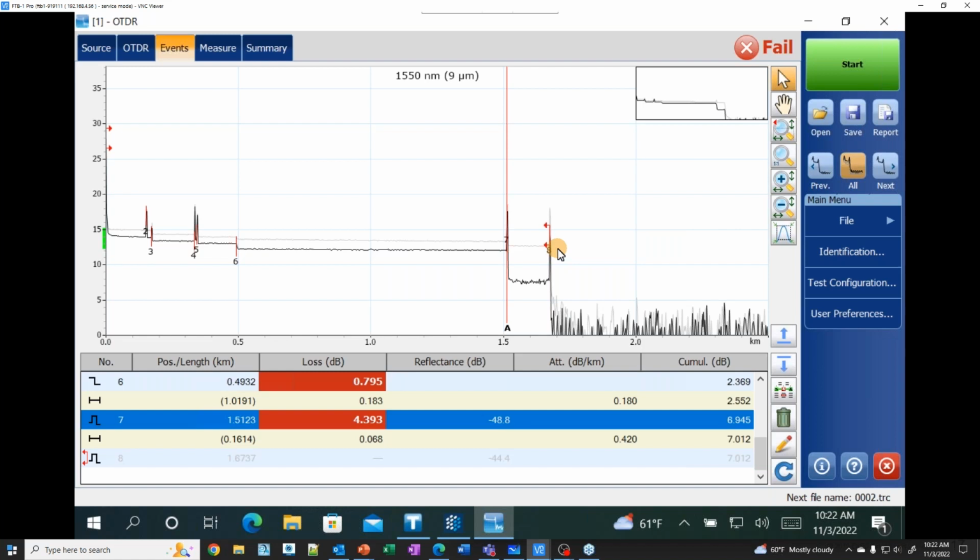There's a fiber management issue somewhere. Could be a twist, a pinch, compression. Could be when you're bonding it and you take your nines and you hammer in your bond clamp and screw it down. Sometimes it'll push up against the ribbon. Things like that are things you have to look out for. And this is why it's important to understand the basics of fiber, because now we can tie this all in, right? So some of the values that I mentioned from earlier, for connectors, for most folks, we're looking at 0.5 dB or better at 1550.